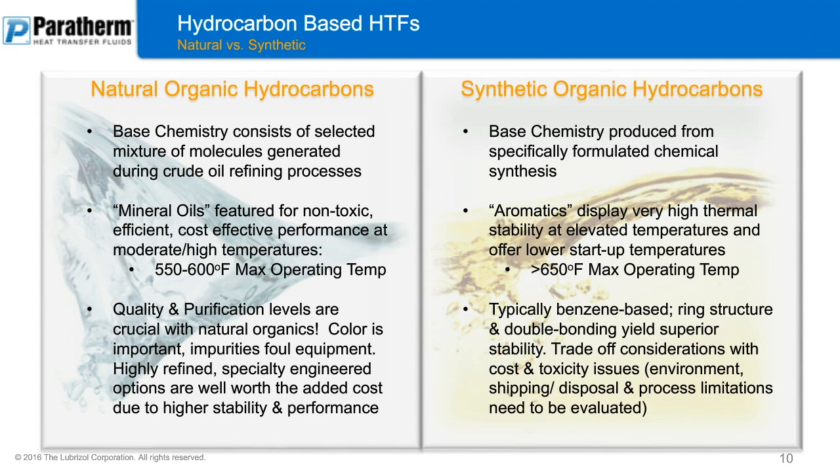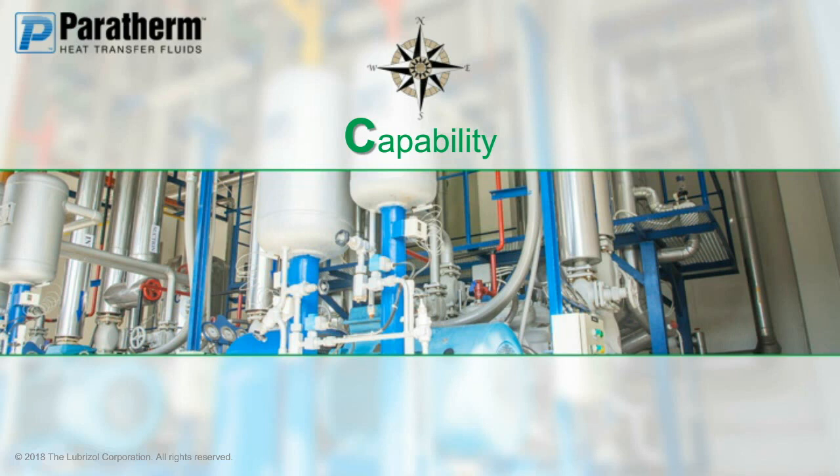Okay, so moving on from there, we looked at classifying these fluids and breaking them down from the highest level. In just a quick review, we have the aqueous-based fluids. If you're anywhere outside of the temperature range of water, or what the temperature base can give you in terms of capability, you're going to experience the issues of boiling, freezing, or outside of the performance areas. So when we look at capability as part of the navigation through your selection process, you really need to take into mind that you have an operating temperature range specific to your operation, and you need to choose fluids that are going to be capable of handling that.